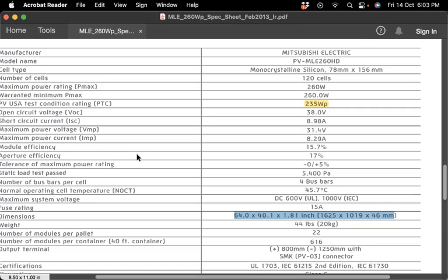As a second level of importance comes dust accumulation, and this is related to the nature of the position where you are locating your solar cell. So if it's going to be located in a desert area, dust accumulation plays a very important role. Wind speed and humidity. Humidity is another parameter that is a function of the location. Whenever you are going to implement solar cells on a site by a sea, for example, or a river, or in any place on the earth where there is relatively high humidity, you should consider it.